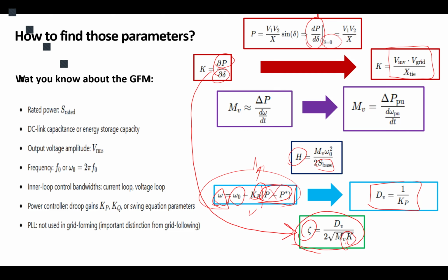So the concept of the filter doesn't mean anything in transient state because we don't have any frequency. Filters respond to different frequencies. If it's low pass, it would let the low frequency pass and high frequency get damped or eliminated. If we don't have any frequency, basically we don't have a meaning for a filter.